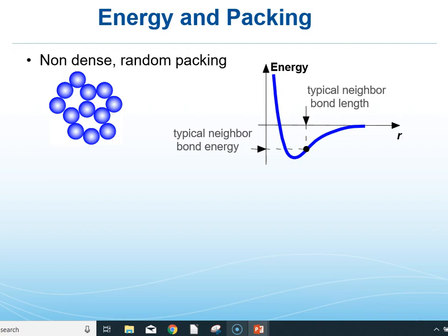Well, if you know that for a given bond the atoms want to be exactly so far apart, no more, no less, well, this thing's everything from soup to nuts. And in fact, it's always going to go towards a little bit farther apart, just because that energy well is not symmetric. So on the average, more of the atoms are going to be farther apart than they really want to be, based on energy minimization of our interatomic spacing versus bond energy diagram, which you can see on the right. So if you look at that blue structure, the average real interatomic spacing is probably where that black dot is. That is not the bottom of the well, so on the average that structure has a lot more energy than it would like to have.